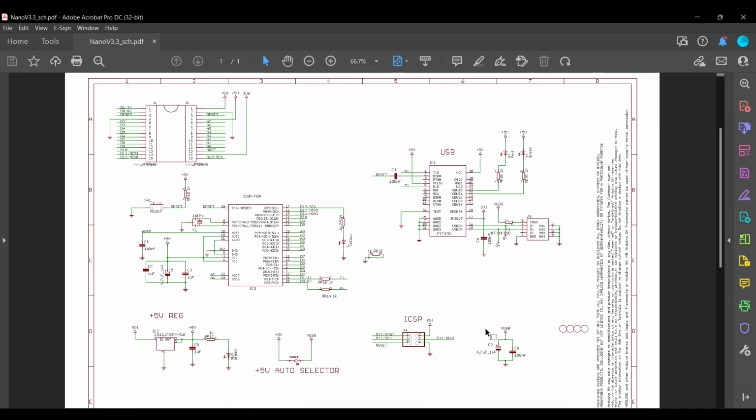I'm going to base my USB miner on the Arduino Nano, but do away with anything I don't need. So I can get rid of the connectors J1 and J2, I don't need a reset button, and I can get rid of the 5V regulator since I'll be powering my miner directly from the USB port. I'll drop 2 of the 3 LEDs as I'm only interested in visual feedback when mining, and this will also keep the cost of the components down.